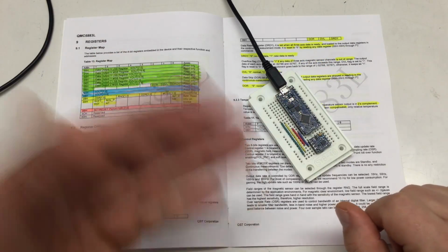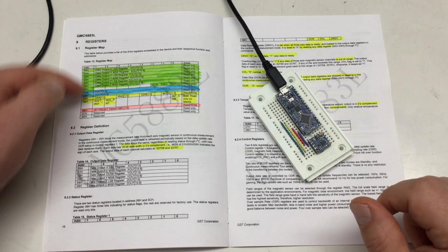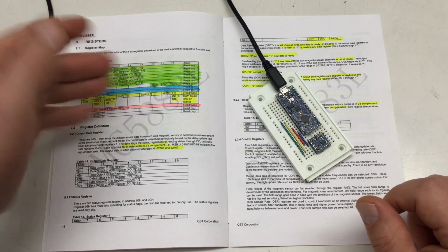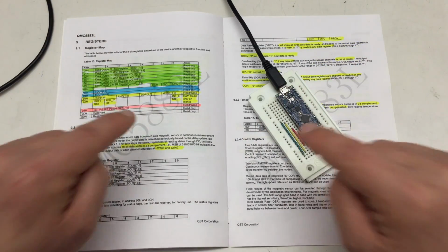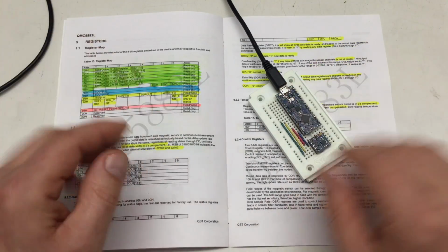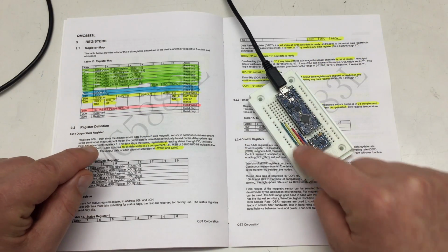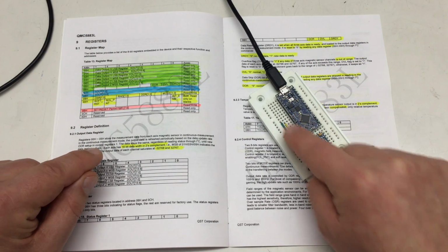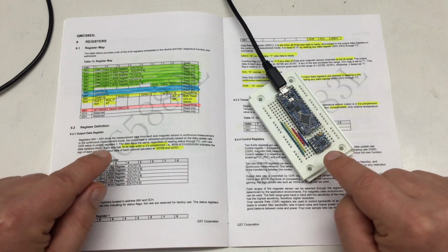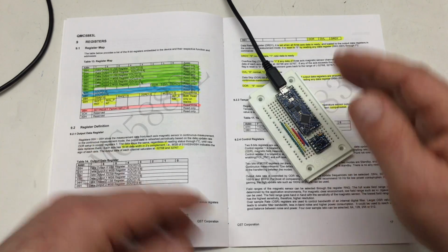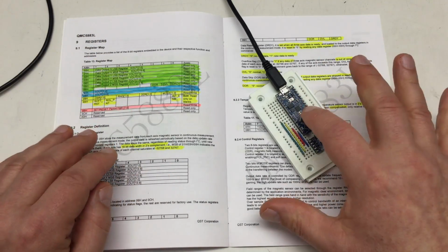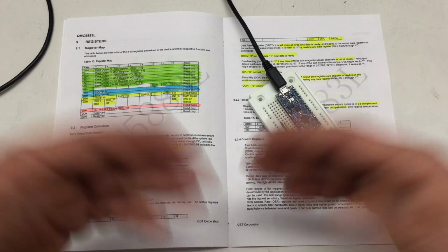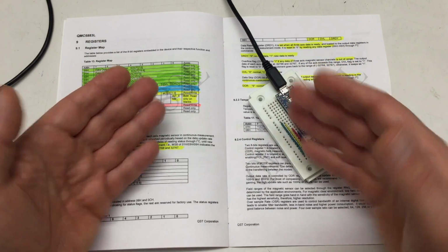I promised you that this time we would read out every last byte that we can get from its control registers, and we'll start out with exactly that. However, afterwards I want to experiment a little bit with the interrupt data ready output of the QMC5883L and try to optimize the communication between the Arduino and that chip using some interrupt routine.